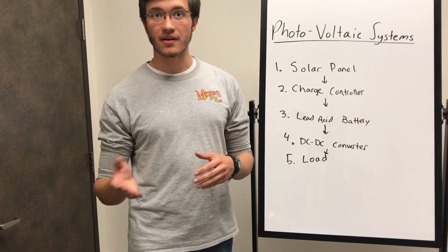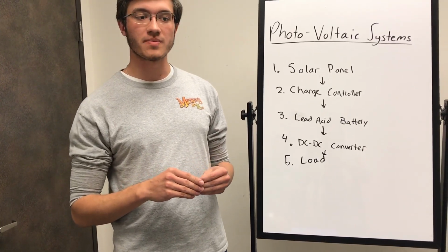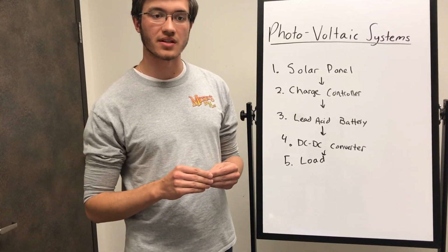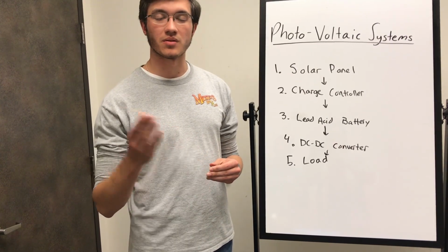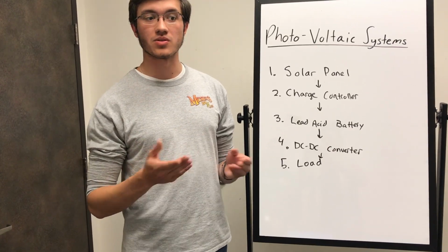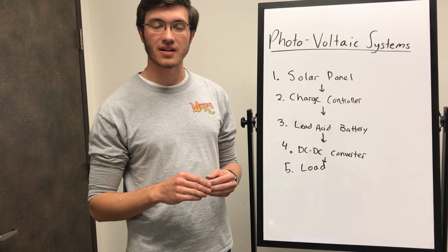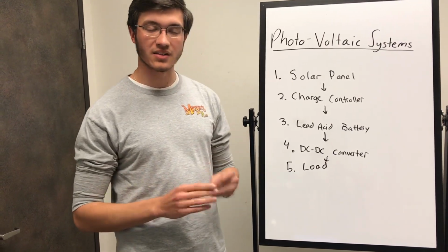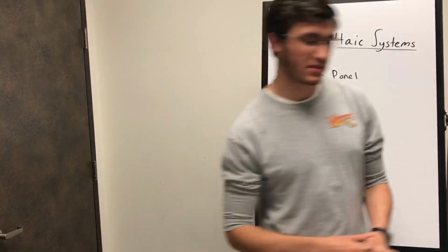And on the load side of the battery, in the discharging, we just need to make sure that we don't over-discharge the battery, because most batteries for renewables will be destroyed once they drop under 20% capacity. And the main way we do that is we measure the voltage of the battery and cut off the load when it drops around 20% and wait until the battery gets charged up again to give energy back to the load. So now that the signal and power is cleaned up, we can start storing it in the battery.